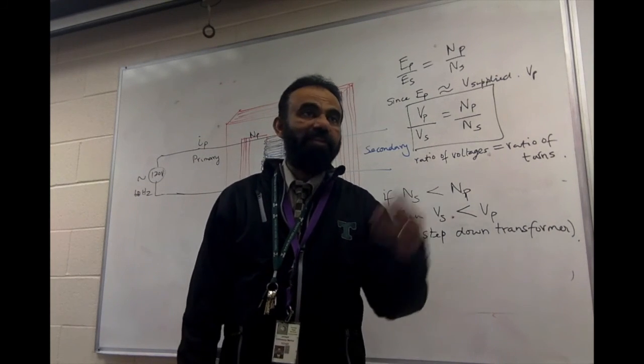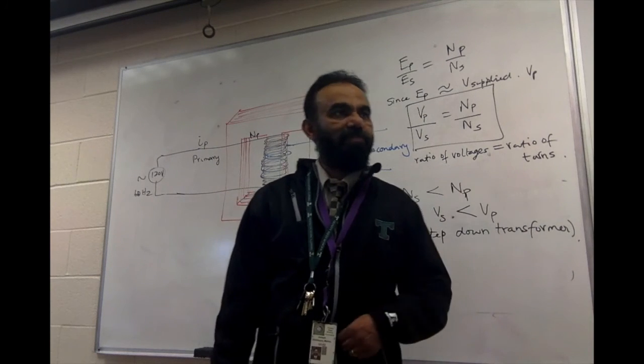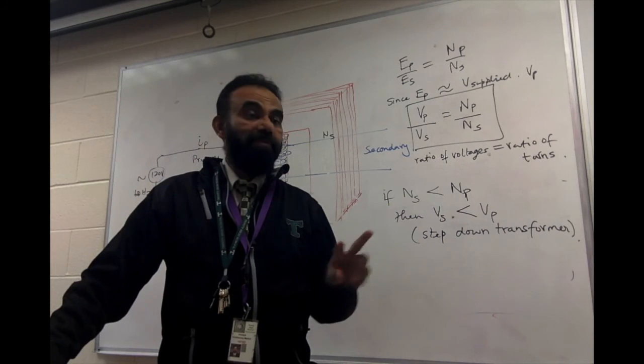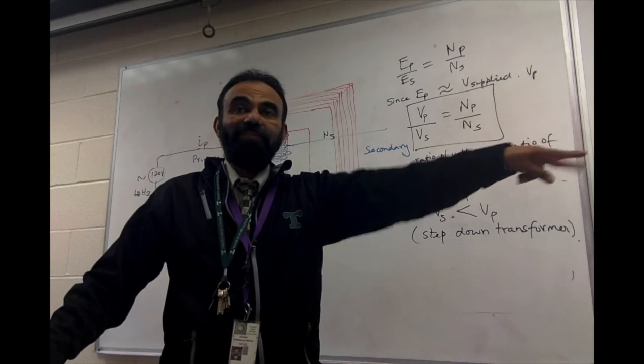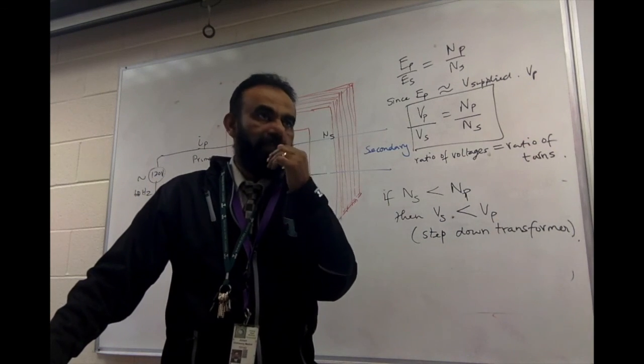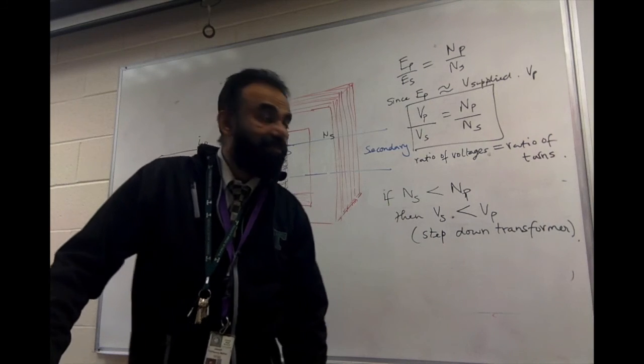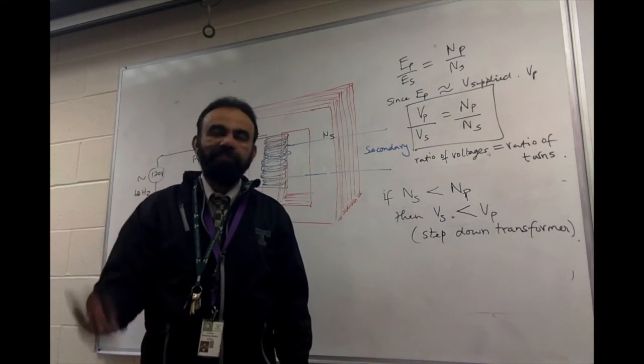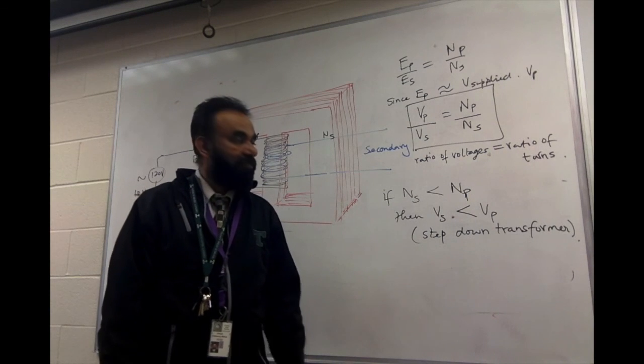But again, limitations are there. You can't take too much power from there. If you really want to take too much power, then hook it up straight to your battery, not through the cigarette lighter. Then yes, you can. There is a certain power specification on the inverter that you can actually use.